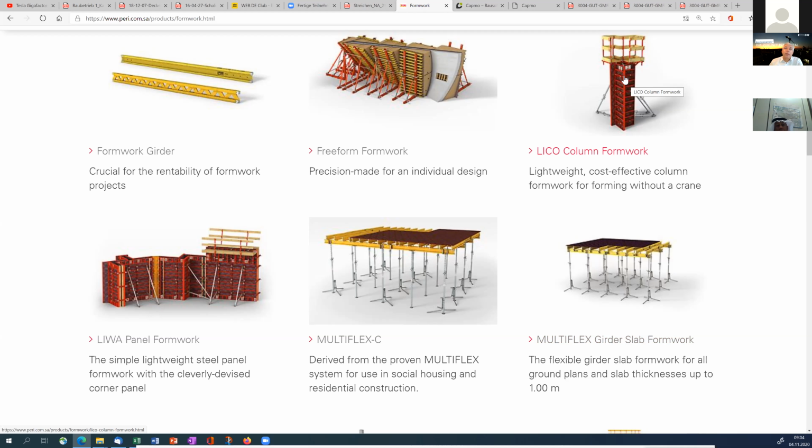Yes, you're right. This is a steel formwork actually. But on top of this, the coating is also plywood, which will be used up to 20 to 30 times. Yes, that's the normal. Wow, 20 to 30 times. A normal timber will take 3 to 7 times max.